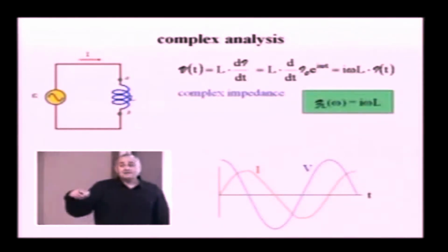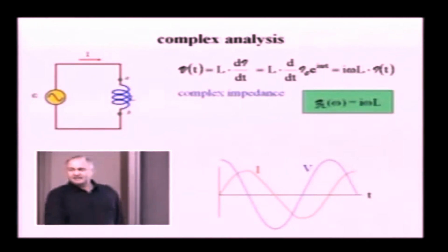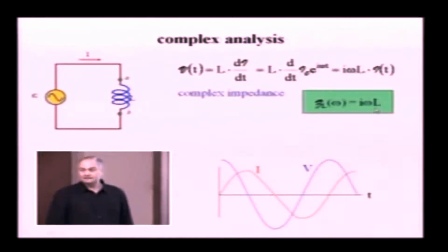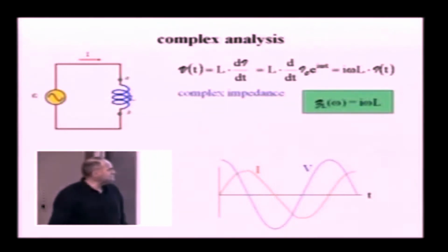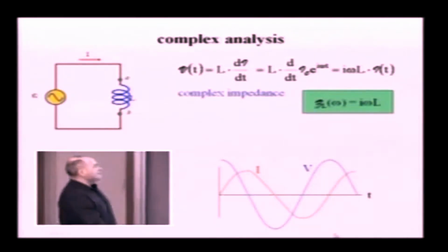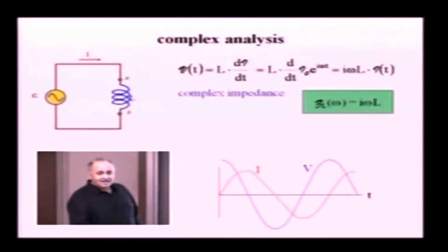Alright, on the previous slide we found actually what is impedance. Can we verify that everything agrees? Yeah, because how from this number do we find impedance? What do we have to do with complex impedance in order to get impedance? Take the absolute value. Correct, you're absolutely right. Okay, so when we calculate the absolute value of a product, it is equal to the product of absolute values.